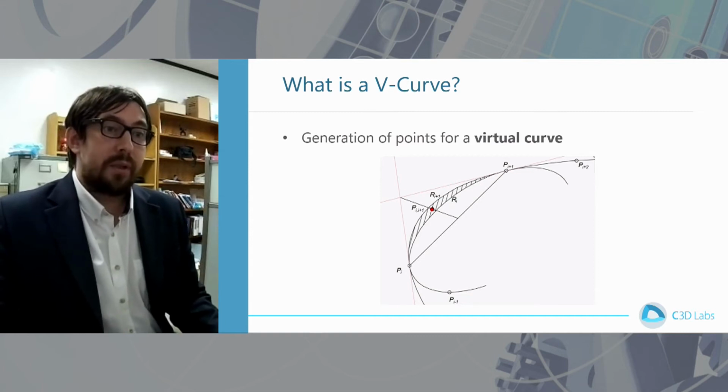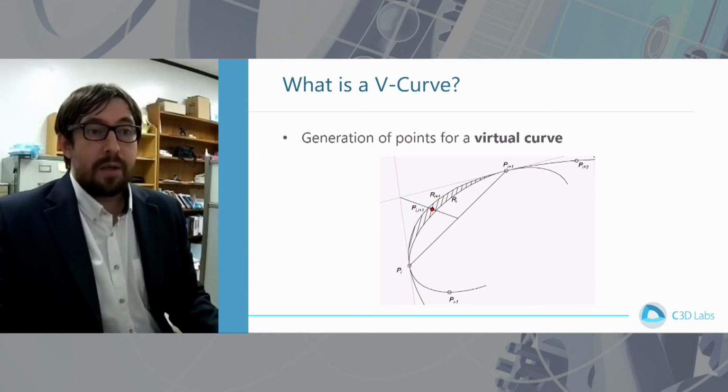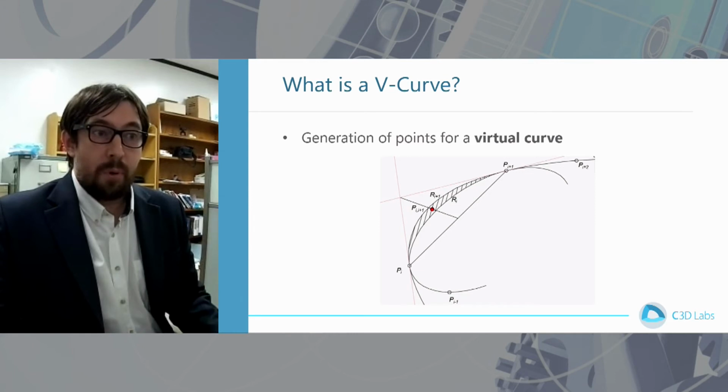The first innovation is that the basis of spline definition is a set of double osculating conic curves on a locally convex base polyline. The adjacent curves form a lens on the polyline segment they share. The spline tension is characterized as the deviation of the adjacent analytic curves of the basis spline. It can be easily assessed visually by the size of the lens between the two adjacent curves.